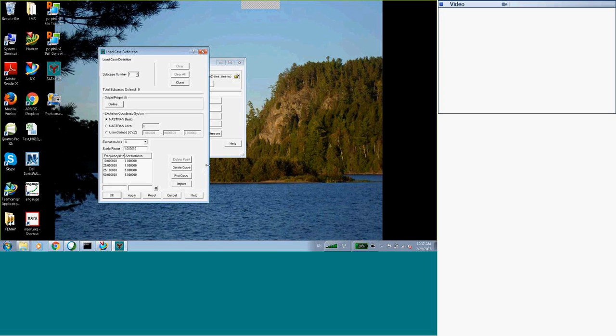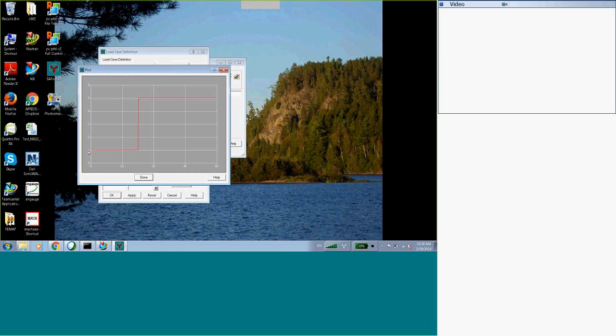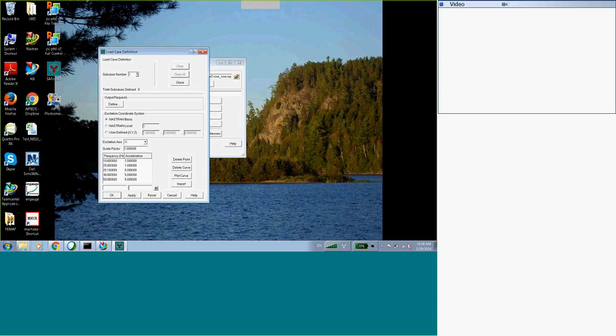So what that is, it's just two columns: frequency versus acceleration. You can enter that manually right there instead if you wanted to. For example, I could add something at 40 hertz, say, to show you 5G here. You can just step it in, 25 hertz, around here. And these are in G. The solution is in inches per second squared, so I have to put a scale factor.